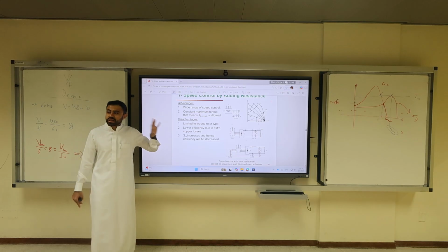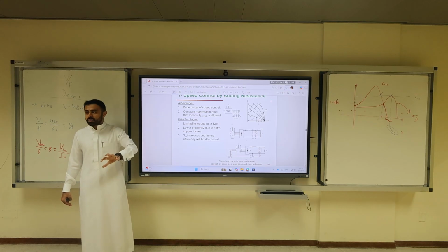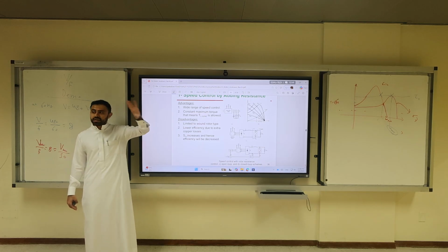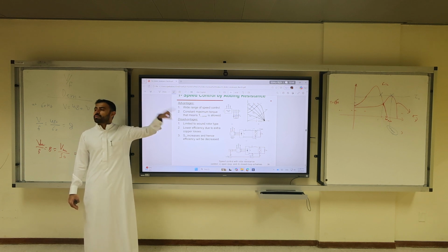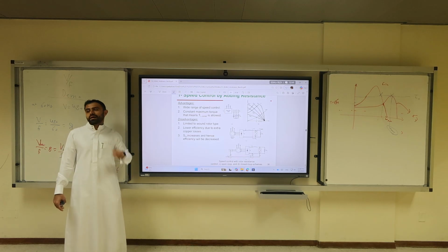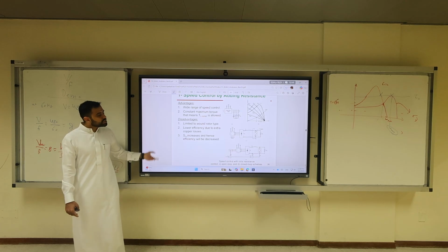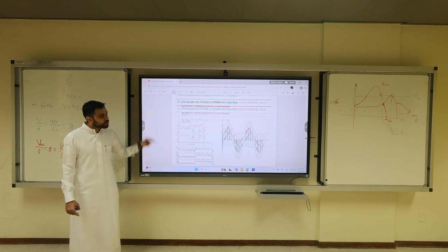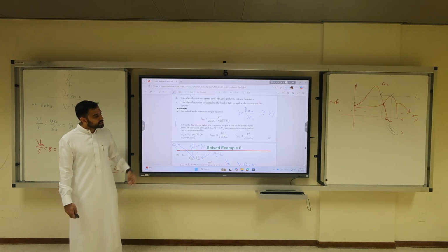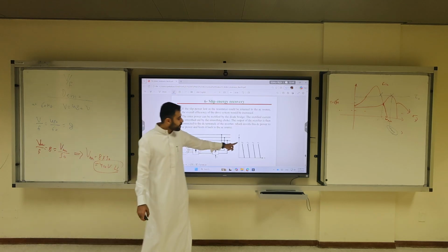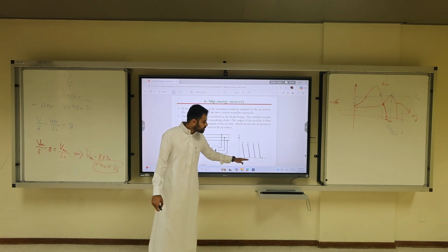What you need to know is that slip energy recovery uses power electronics with firing angles to change the effective impedance seen in the source, but with that impedance seen in the source, you lose energy in the supply. You don't lose it in the motor itself, and you retrieve it back. So that's energy recovery. It's a very smart technique, but the downside is it's only for wound rotor. It's not used for squirrel cage. Okay?